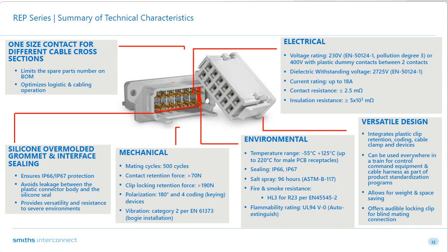Because you remember I talked about in one of the previous slides that these connectors are often behind either cabinets or often, I've seen in examples where it has been an interconnect solution left in kind of open weather, if you like. Open weather doesn't mean completely outside, but in areas that's not nicely sealed or behind a panel. Now, in pretty much all environments that I've been to with HVAC systems, one thing is common. The temperature and the humidity often is high in these sort of environments. And it doesn't take long for this humidity to reach a dew point and condensation starting.